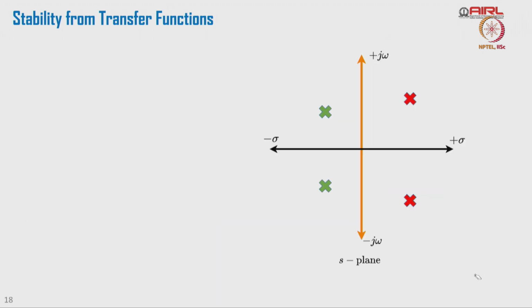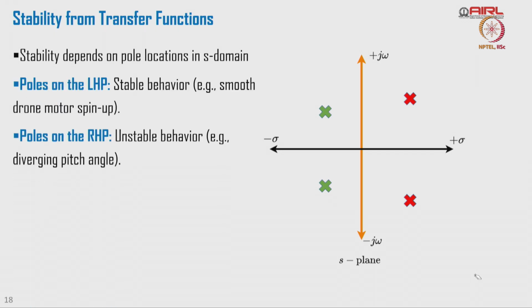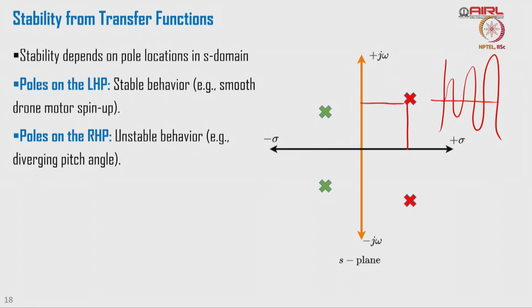Now, what is happening here? We are putting some poles in the right half plane. What will it give us? It will give us some unstable behavior of the system. The response of the system will become something like this. It is a kind of growing oscillation. Why oscillation? Because of this imaginary part, and the real part becoming positive will give a growing oscillation.